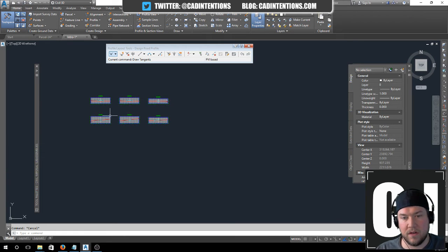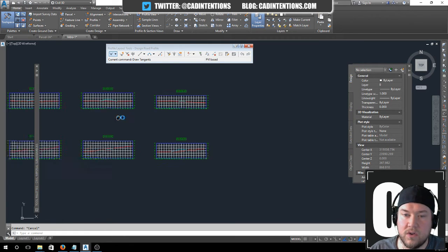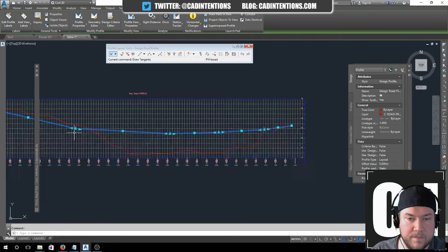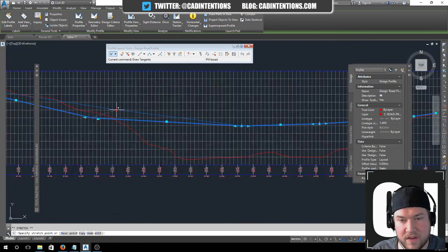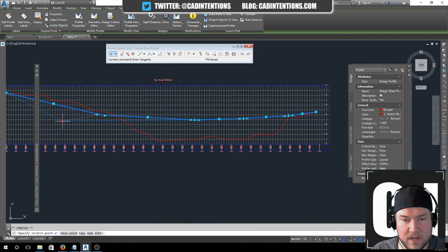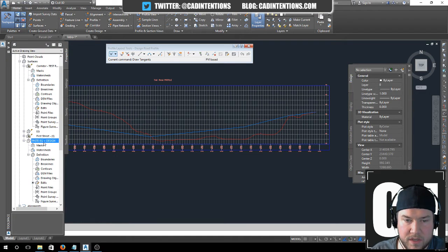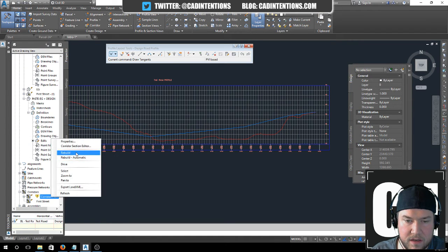There we go, we've got cross sections, and again, all of these things automatically update when you change your profiles, which I just find super useful. If you want to cut way in, sure, we've got more. Let's fill. You can see I've pretty drastically changed all of that.